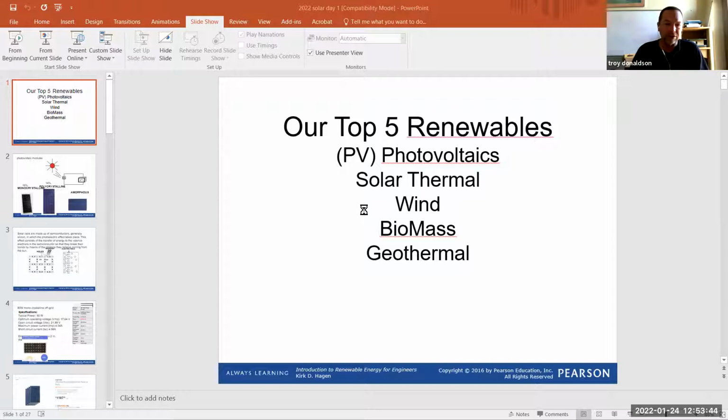80 watts, not much. And then you can see what kind of amperage we get. That's maximum power current at 4.54. So that's pretty low amps. Like if you think about your home and the amperage that you can carry in just a basic circuit in your home, which is 120 volt, that's like 15 or 20 amps, right? So this is 80 watts, pretty low wattage, and pretty low amperage. In other words, not a lot of current is flowing. And that's typical. That's why we have arrays of these things to up the amperage and up the wattage.